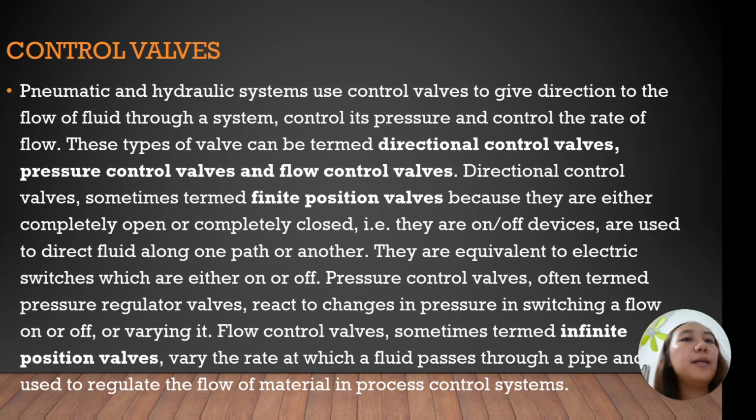Control valves. Pneumatic and hydraulic systems use control valves to give direction to the flow of fluid through a system. They control pressure and control the area of flow. These types of valve can be termed directional control valves, pressure control valves, and flow control valves.